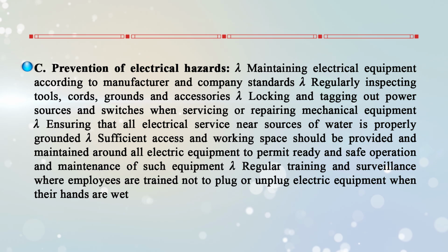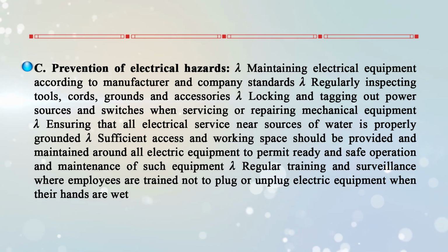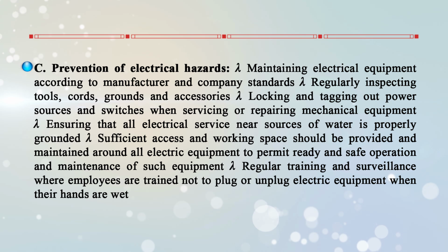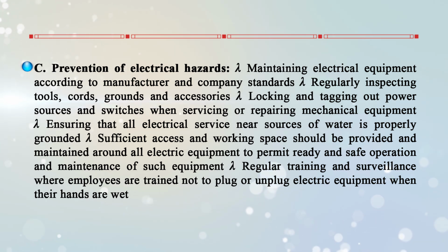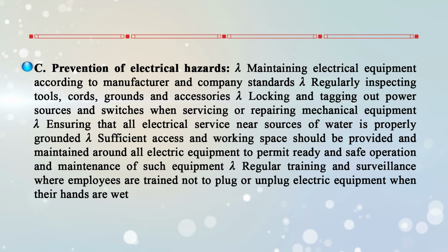And sufficient access and working space should be provided and maintained around all electrical equipment to permit ready and safe operations and maintenance of such equipment, with regular training and surveillance, where employees are trained not to plug or unplug electrical equipment when their hands are wet.